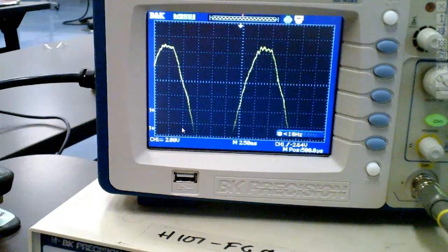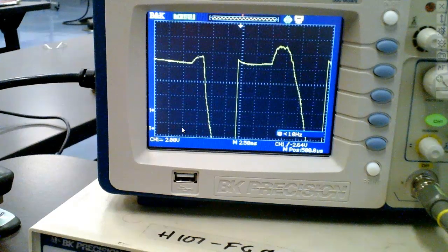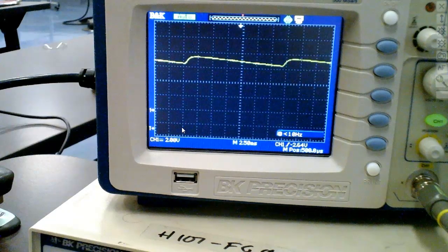I'll have to do that another way. But what would happen if I come over here and take the load out? We get pure DC now. But now we're not loading the capacitor at all, right? You understand? So this is really nice DC right here, right? As soon as I hook up a load, then all of a sudden my DC goes down, and we can actually see. We call this a ripple voltage, and it varies with load.